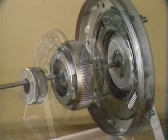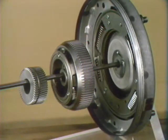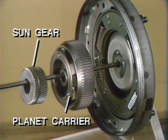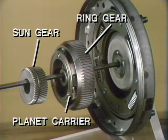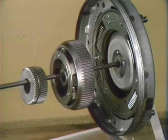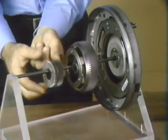The new parts are the splitter planetary unit, composed of a sun gear that splines into the turbine hub, a planet carrier assembly that drives the intermediate input shaft, and a planetary ring gear that is splined into the damper in the converter cover. The damper, similar to the damper in the automatic overdrive converter, cushions the mechanical input drive.